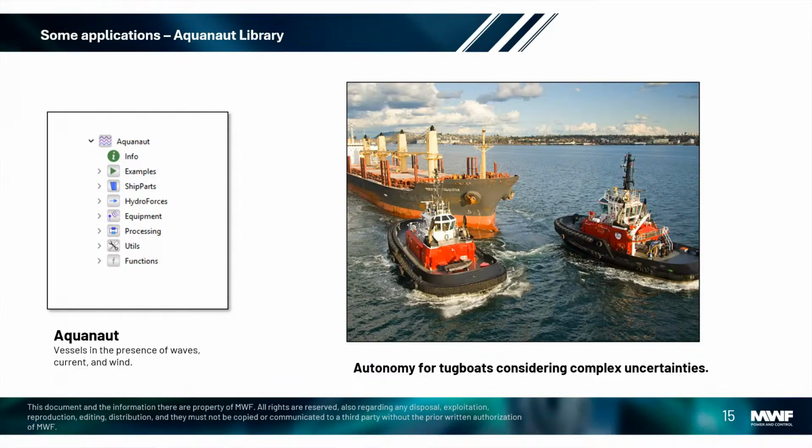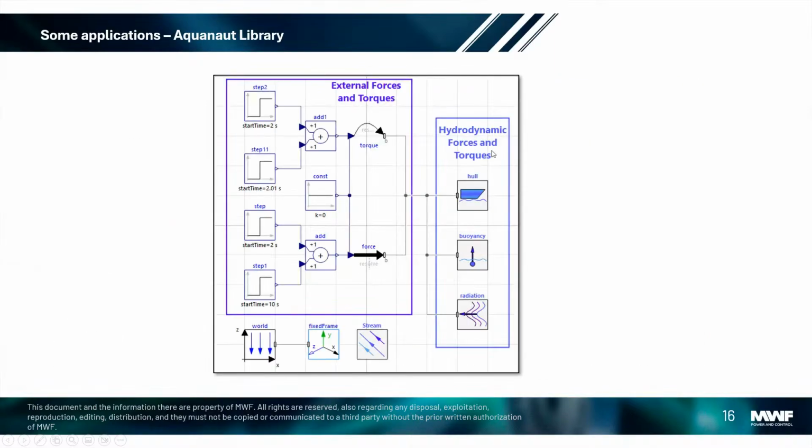But as you can see, it's able to simulate the contact between a vessel, a pure hull, with the water, and it computes buoyancy, radiation-induced forces, viscous-dependent forces, and so on. This is how it looks like. These components here at the right side are a hull, buoyancy forces, radiation-induced forces, ocean currents in this block here called stream.